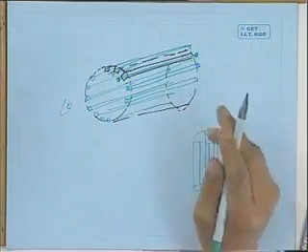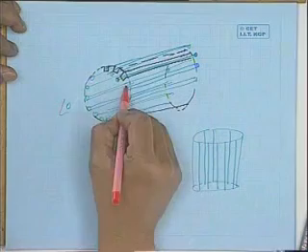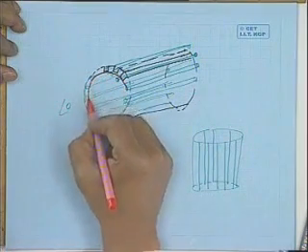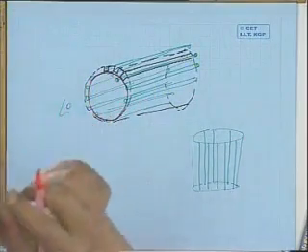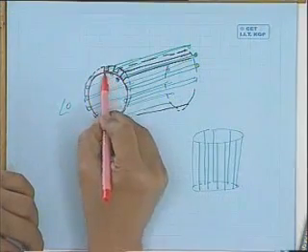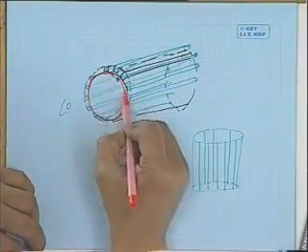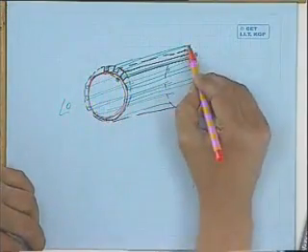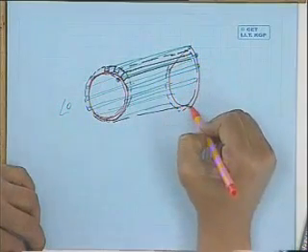And the extended ends of these conductors are shorted by two end rings. You take two copper rings or aluminium rings, continuous rings, with holes so that you can insert the ring onto each of the conductors, such that all the free ends of the conductors are shorted, as if you had joined all these ends by wires.